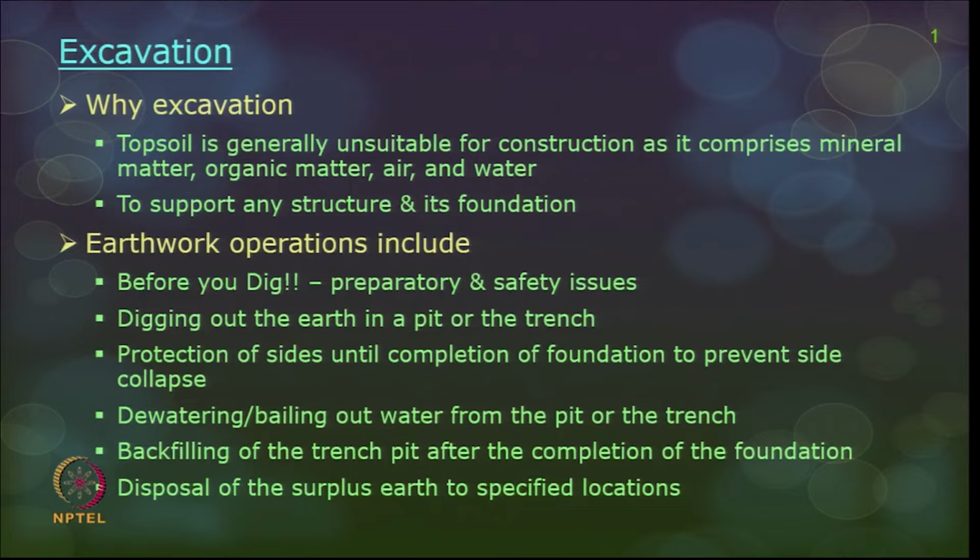Then whenever you encounter a water table, dewatering or bailing out the water from the pit or the trench, then backfilling of the trench or pit once the excavation or foundation is completed, and then you dump the surplus earth into some specified or marked location. So, these are all the different steps you have in earthwork operations, and now we are going to see the different hazards in all these steps. Now, let us start with before you dig, what are the major precautions you have to take. Okay. And before understanding that, let us discuss something on the IS code and what it says about types of soil and types of excavation.